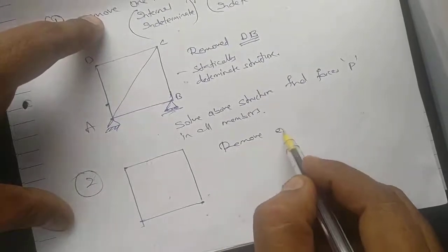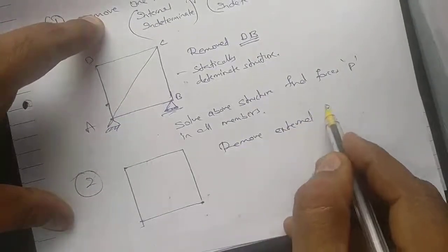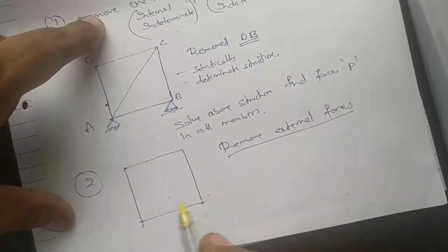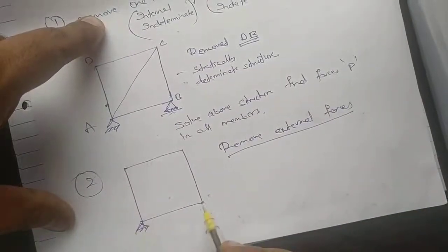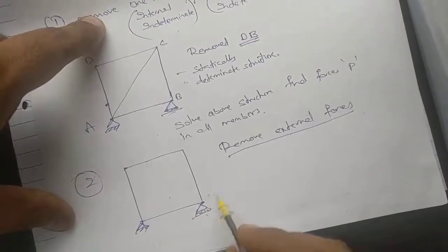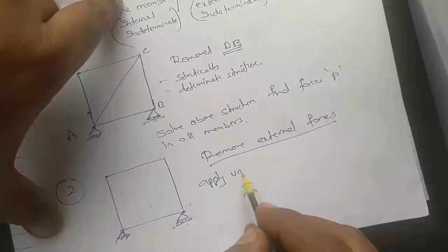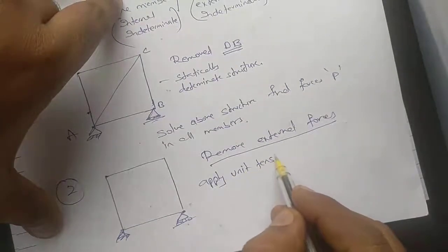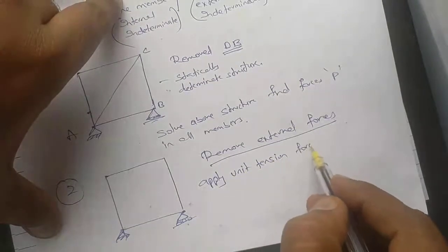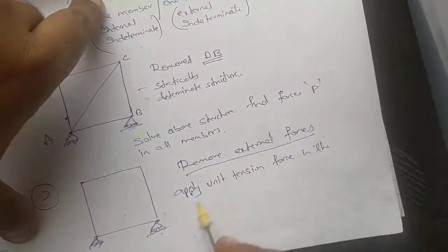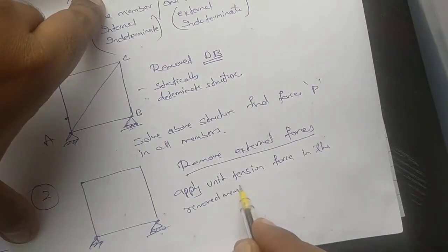Remove external forces and apply unit tension force in the removed member.